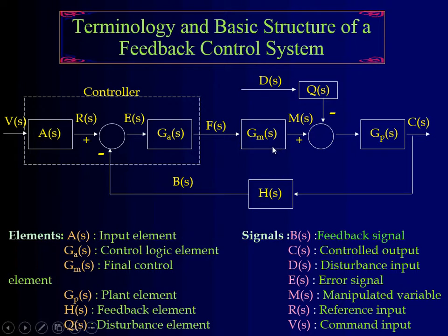And that event is called a disturbance. So what happened is that this again, the disturbance in here, acts on your system, and what the system ends up getting in the form of a control signal is the difference between what the control wants it to do and this disturbance signal.